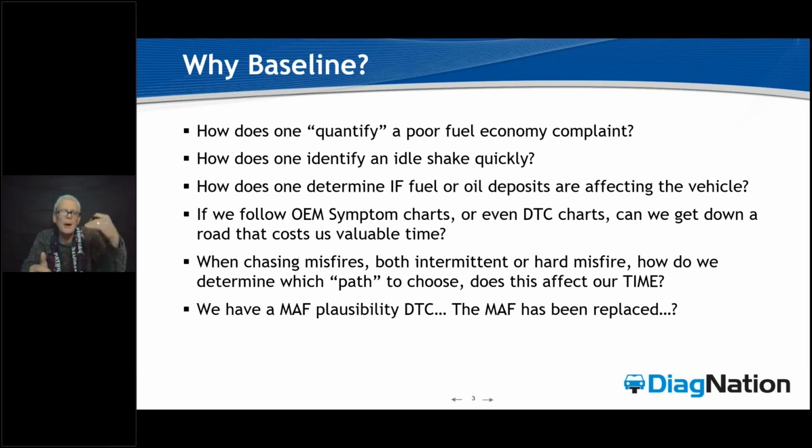Well, the problem is that you or I get in that vehicle as a technician and we go belt the gas and get down the road in the car, and it seems to want to rip the tires loose against the traction control. So we come back to the shop, look it over, check it for codes. There's nothing wrong with the car, and it seemed to have all kinds of power, so we do a no condition found. But yet that customer's back 3 or 4 weeks later going, you know what, guys? I'm telling you, this thing just doesn't have the guts it used to. This is something we can see with baselining if we're keyed into how it works and what we should be expecting.